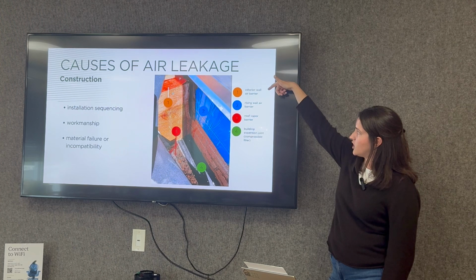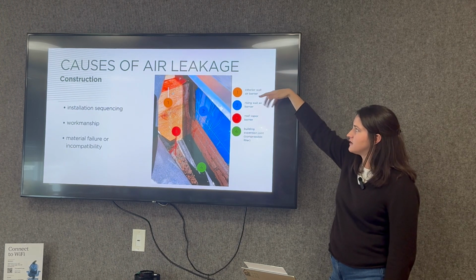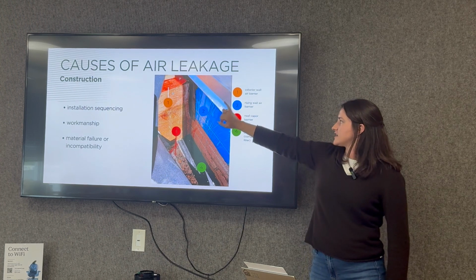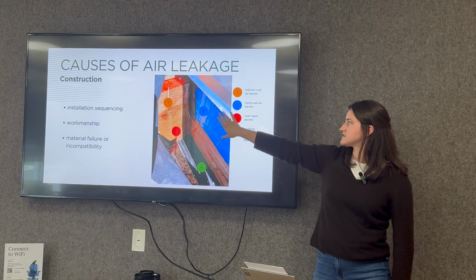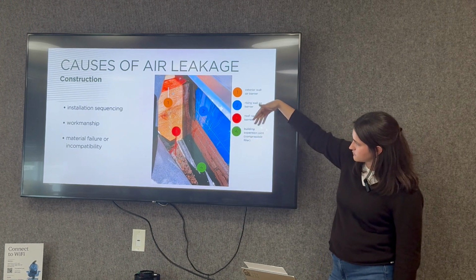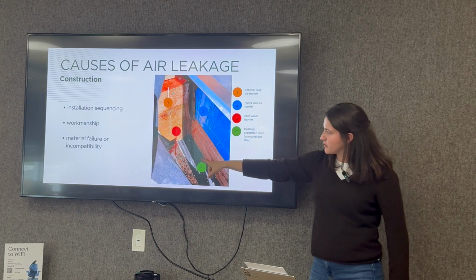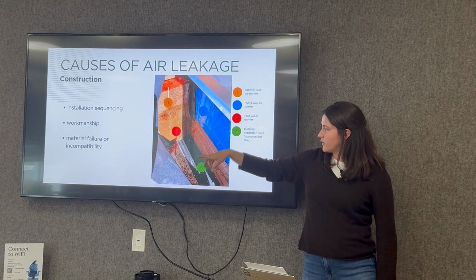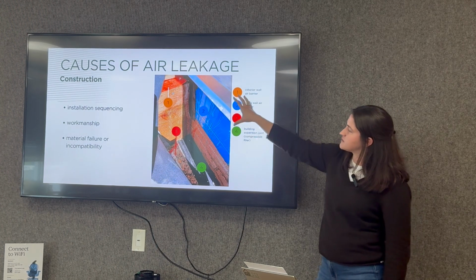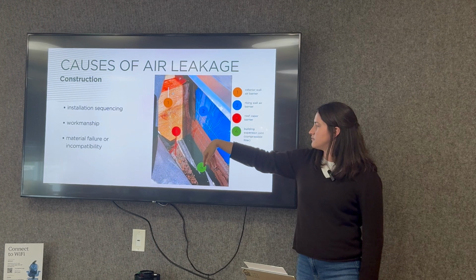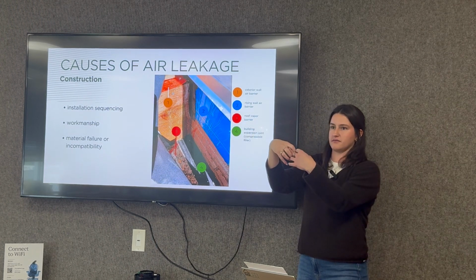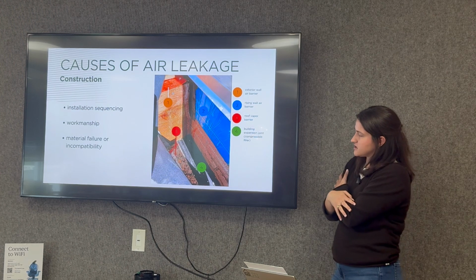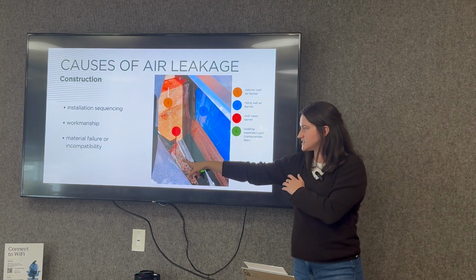As you can see, the wall membrane installer did his job, kind of, and installed the wall membrane up to here, within the general vicinity of the corner. The mason installed his self-adhering air barrier membrane below the new flashing, and then the roof vapor barrier is also installed on the concrete roof deck, and the building expansion joint, the compressible filler, is here. And the way this detail was designed is that all of these materials come together and essentially die into this compressible joint, which would then make this corner airtight. So in this instance, the roof vapor barrier is acting as our air barrier.